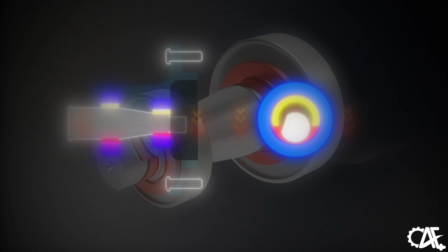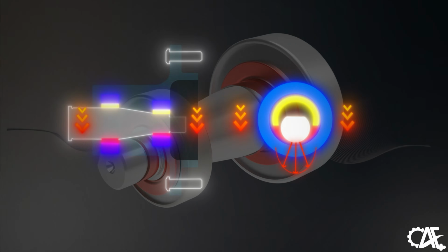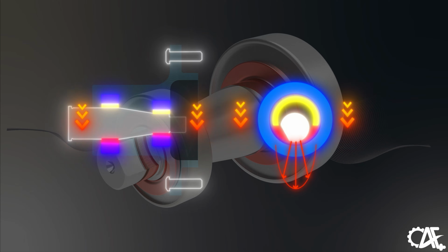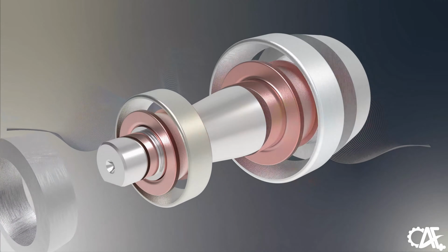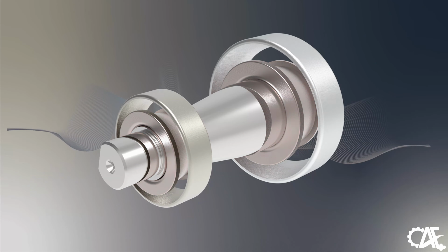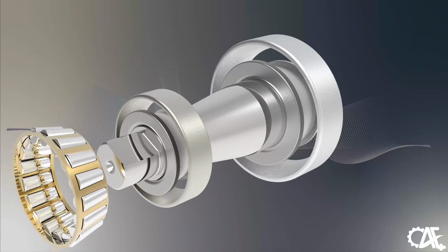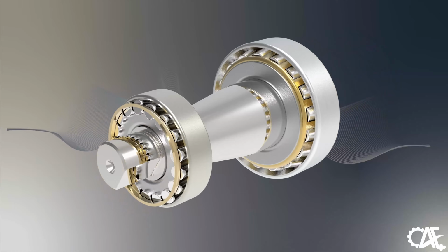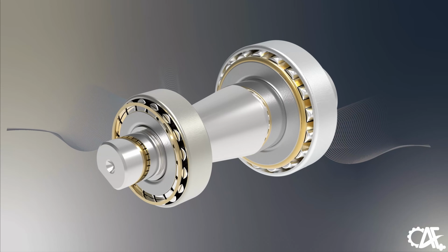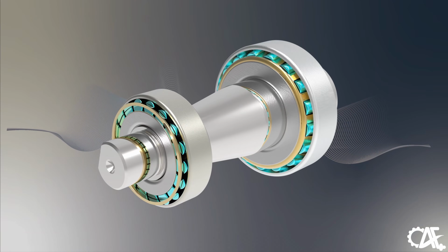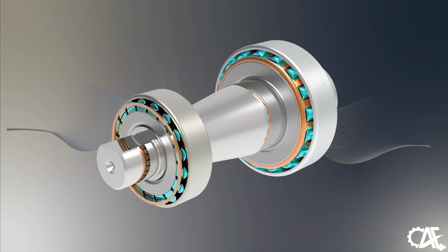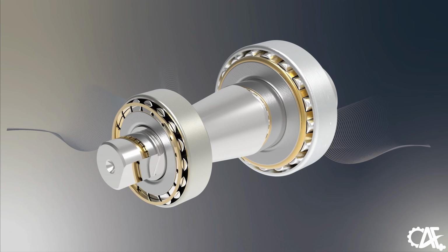These bearings relied on sliding surfaces, which led to significant friction and heat generation, ultimately restricting their efficiency and causing wear and failure at higher operating speeds and loads. To address these challenges, the rolling bearing was invented as a groundbreaking solution. The rolling bearing was designed to reduce friction and enhance load carrying capacity by introducing rolling elements between the inner and outer rings.